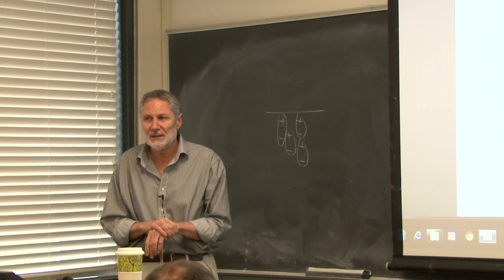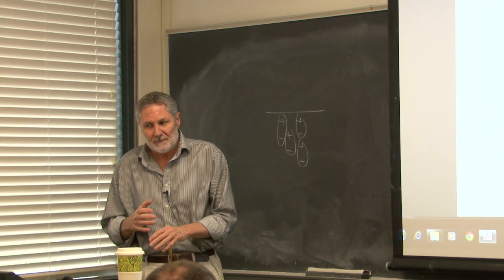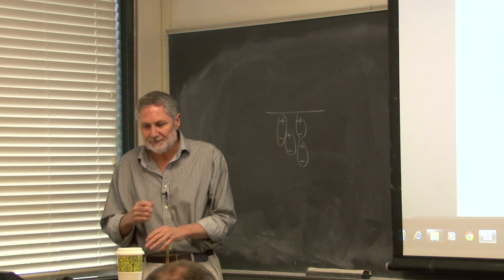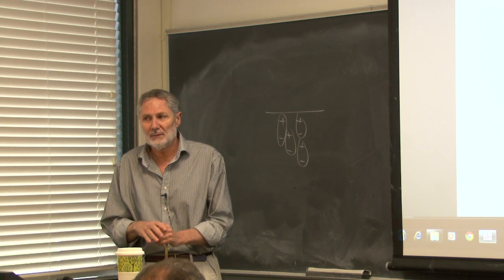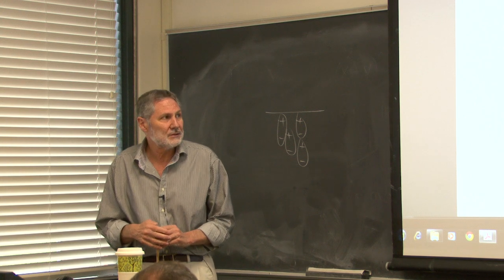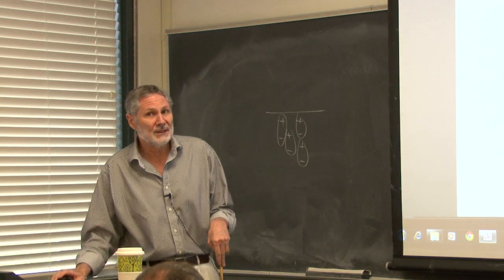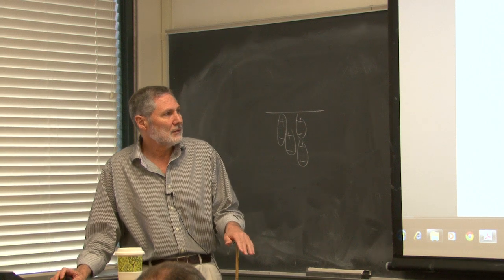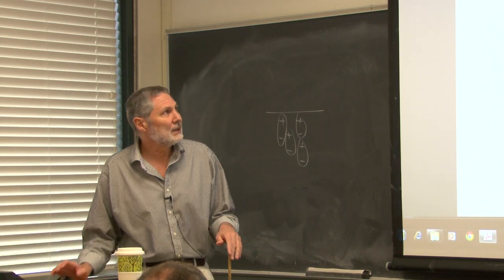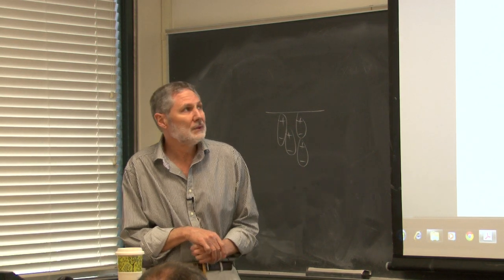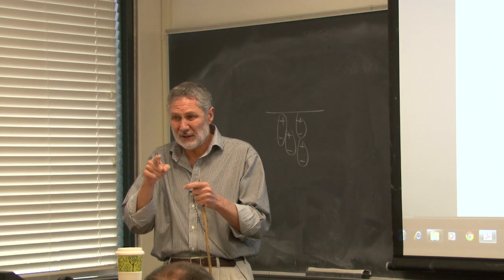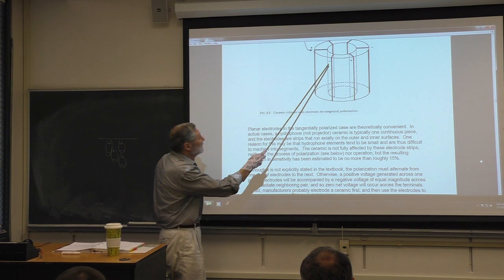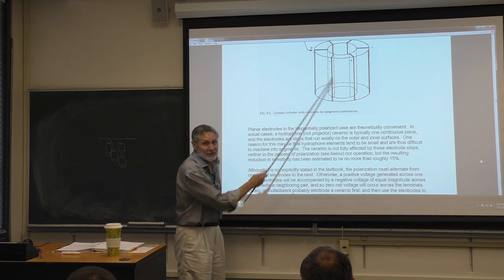Projectors, I think, because you want to get a lot of power out, tend to be genuinely segmented. And they may always be segmented, I don't know. But it's a common trick in hydrophones not to segment them, but to just have the conductor on the outer surface here. It doesn't penetrate through here.